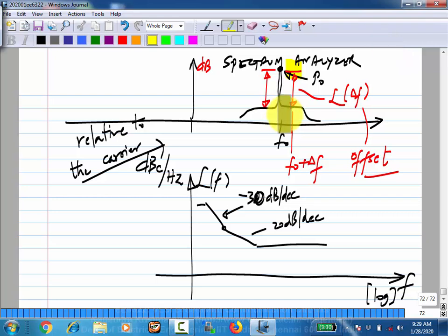In measurement you can use the spectrum analyzer. Now a spectrum analyzer is not the ideal method, because any noise, either amplitude noise or phase noise, will show up here. But we'll assume that close to this it is all phase noise. Or you can use the phase noise analyzer. From that you can get the phase noise plots and then integrate that to get the jitter. Any questions? There are a couple of problems in the tutorial. I think once you go through the calculation, you will get used to this type of calculations.